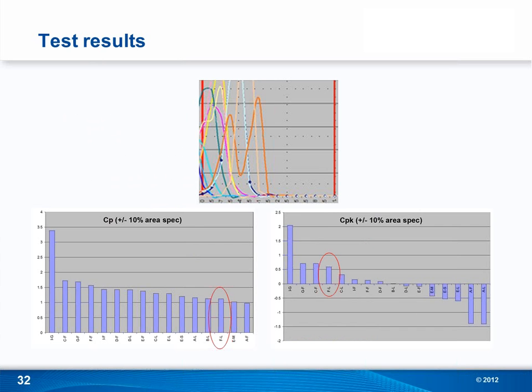To take another look at that, the possible reason for this double hump may be that the operator changed the power while he was cutting this stencil. What he could have done is cut all the smallest apertures with a different power and speed setting than the larger apertures.